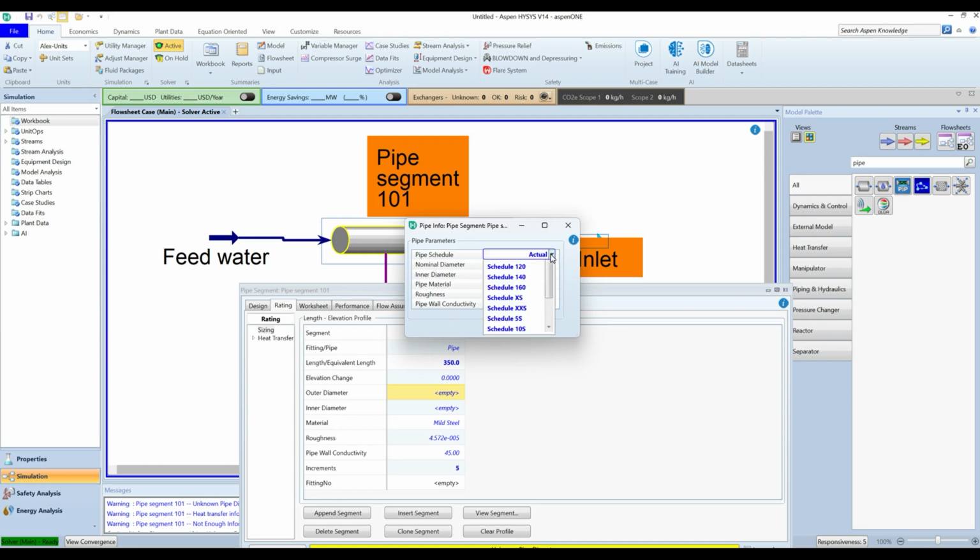And then we're going for a schedule 40 pipe. And then the nominal pipe diameter, we remember I said it was about 50 nominal bore. Then you get 50. And then the program will calculate the internal diameter of the pipe, which is 52.5 millimeters. And then once you've done that, you've done pretty much the minimum required for the pipe dimensions.